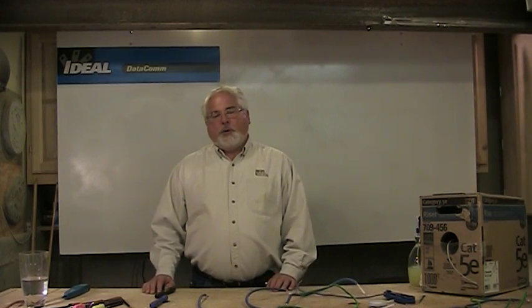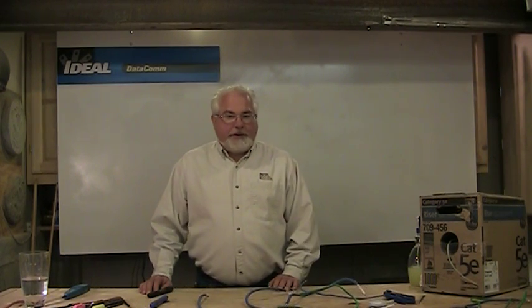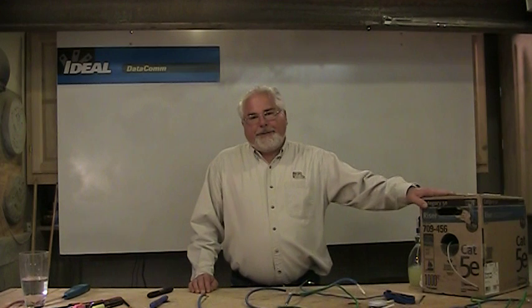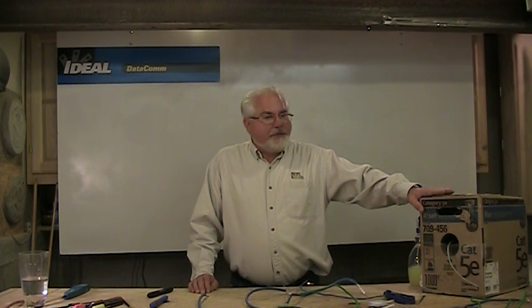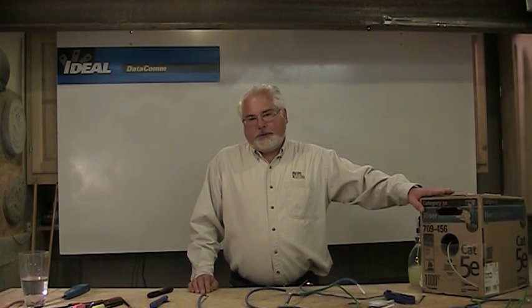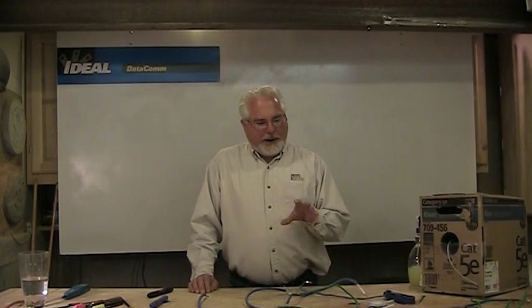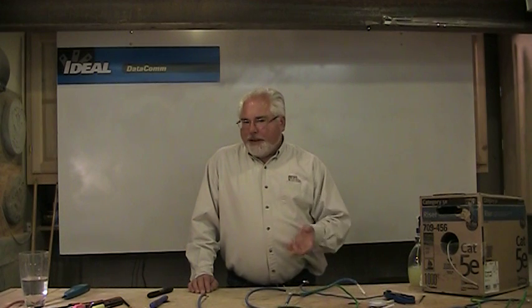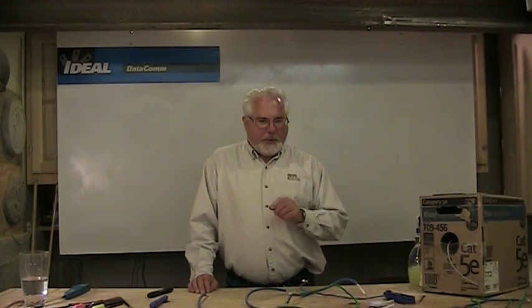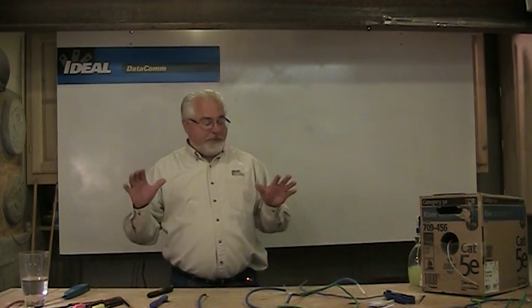Now you've taken a quick look at the 3 basic category 5E, Cat 6, Cat 6A wires we have available in the industry. Let's talk about some of the similarities in all these wires. When you look at category cable, as a general rule, you're going to find it's twisted. Obviously, you notice that when you look close up at it. How we twist and how much we twist has a lot to do with the cable's performance. A lot of us don't realize that all wires are engineered in a certain shape, and if you mess with that shape, you mess with the performance of that cable. So we don't want to deform the shape of the wire, and untwisting of pairs is a big one.